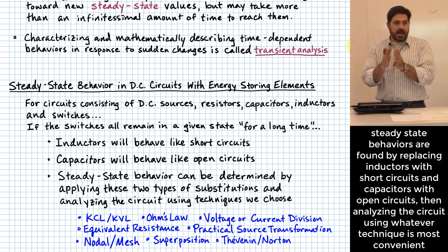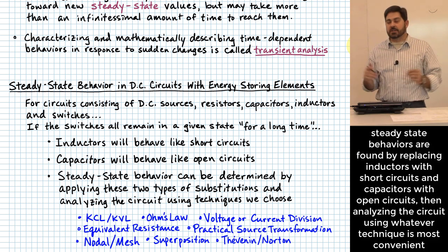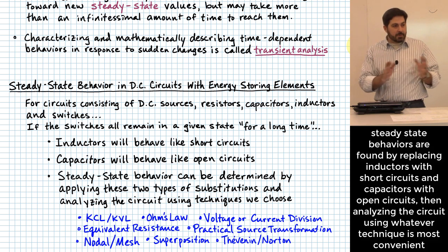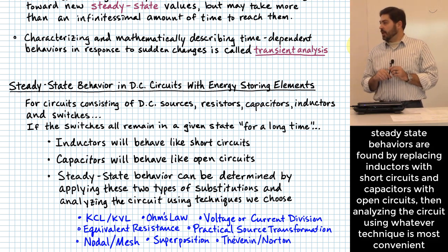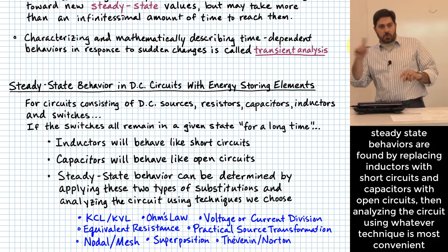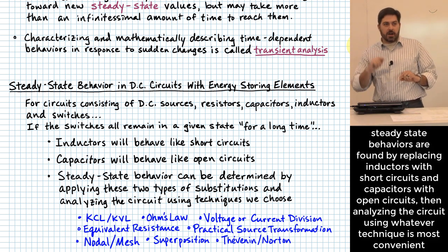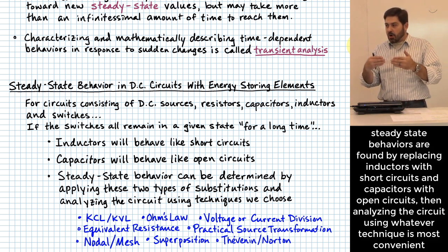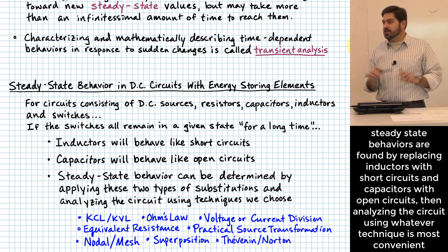And so for a capacitor, if you just leave it connected for a long period of time, any sort of time-dependent effects will go away and the capacitor will start to look like an open circuit. So these two rules, that inductors will start to look like short circuits, meaning just a wire, and capacitors will start to look like open circuits, meaning no connection at all, if you leave them connected into a DC circuit with no changes happening.